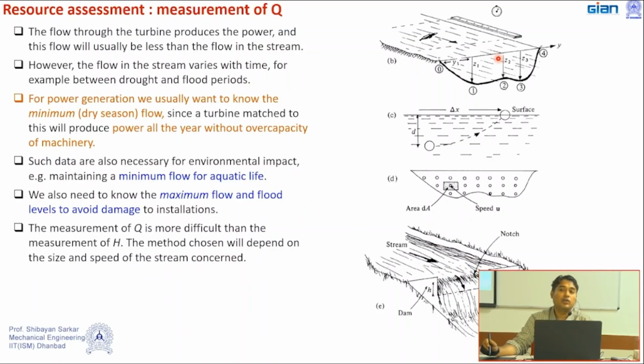And I have told you in the last class also, even if the designs of the wind turbine and this hydrokinetic turbine both look the same, there are certain application differences. Here we are certain about the direction of the fluid, but the restriction is we will get a very narrow area, a narrow depth, to apply your hydrokinetic turbine.